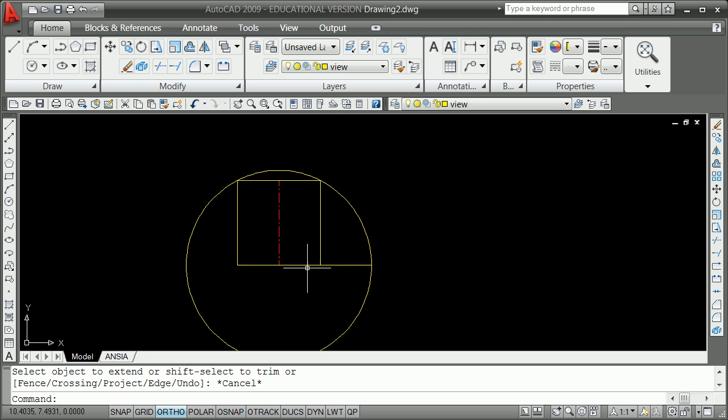That's it. So I'll show that again. I'm going to do U for undo. You do EX, spacebar, screw that. Hit that there as your, sorry, did it wrong. EX, spacebar to screw that and push out to where you want to go. You can get rid of that circle now by, however you know, clicking on it, typing an E.